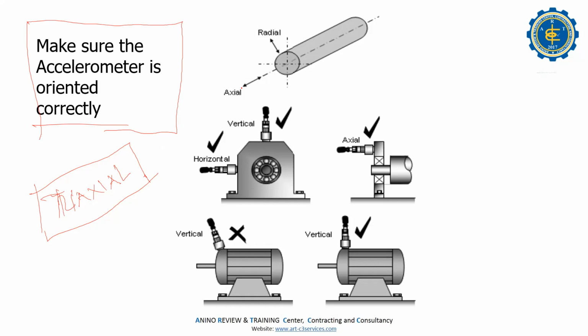It just captured the horizontal and the axial. So the analysis is the same or different? Sir, analysis is the basic. Everywhere it is the same. The thing is the equipment, how easy it makes your data collection. That's the advantage of triaxial.